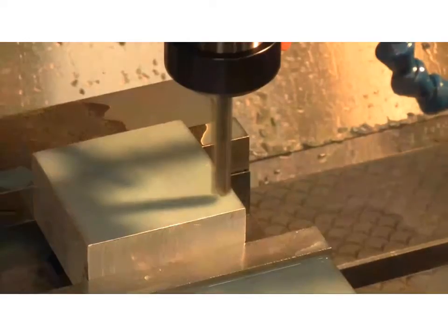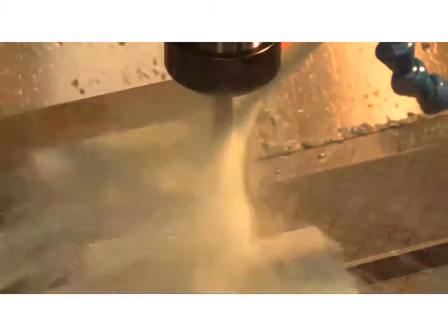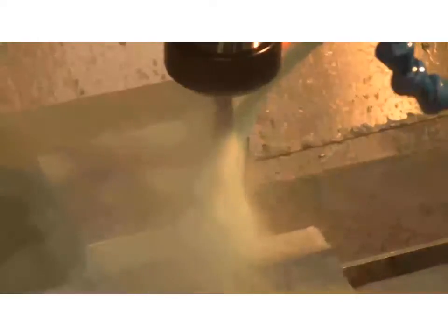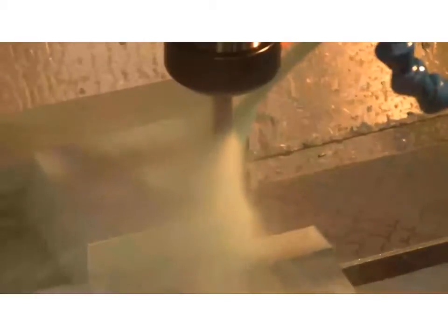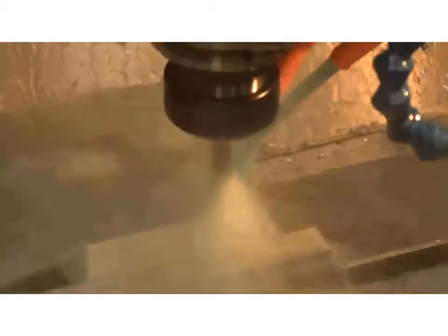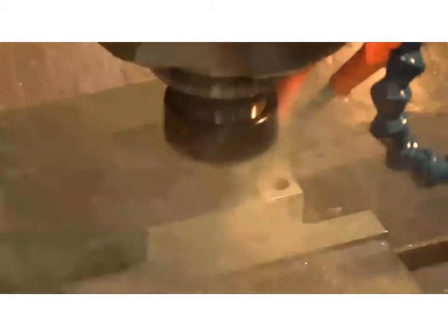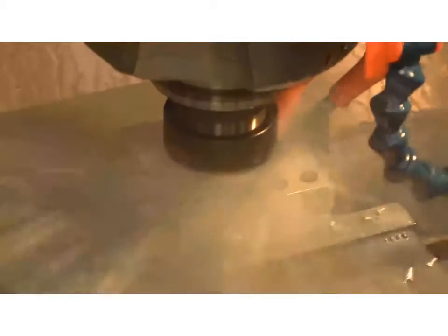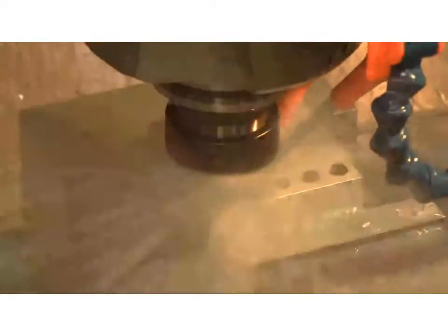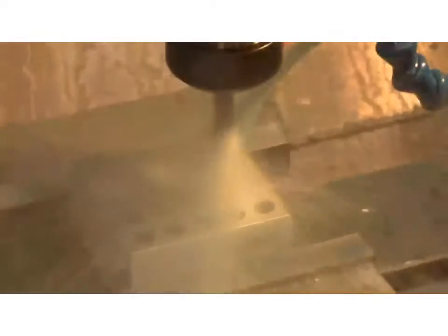Okay, I'd like to give a special thanks to Morrison Tool Company for allowing me to do this video. This is their 3-tooth Aluma drill, and of course it's drilling in aluminum. But what I thought was interesting here is that we don't have through spindle coolant. We're just using a regular coolant line, and you can see we're blasting through that quite fast.